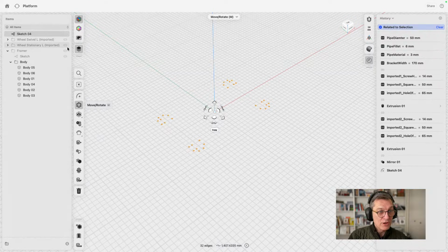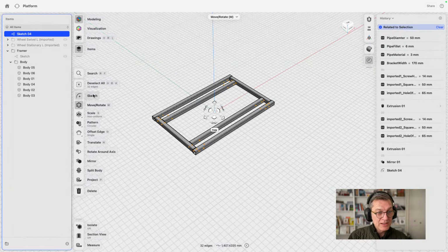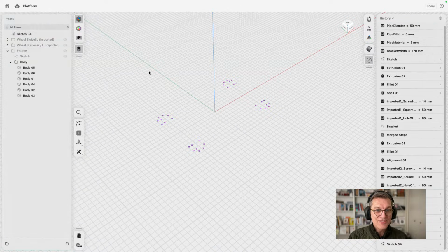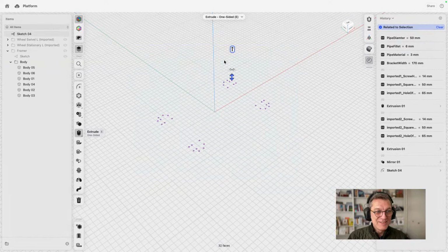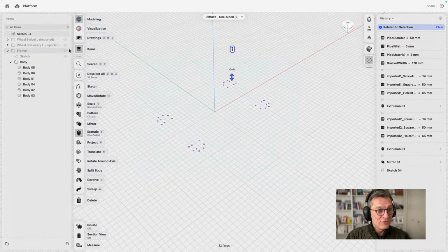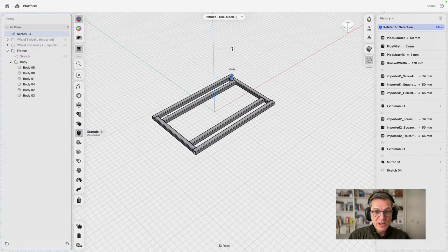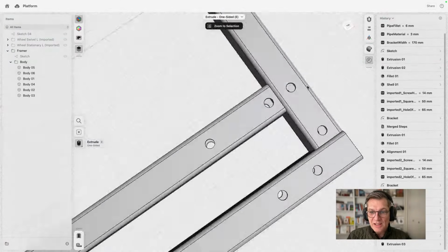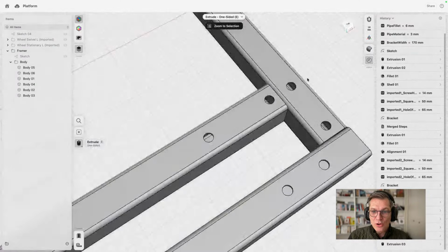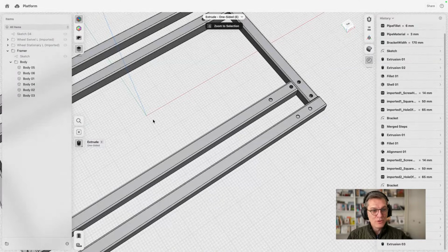And here it comes now. I show my frame. Then I did something wrong because I just selected edges. I didn't want to select just the faces because then it triggers the extrude command, show the frame, extrude this one up. And there it cut all these holes through it.